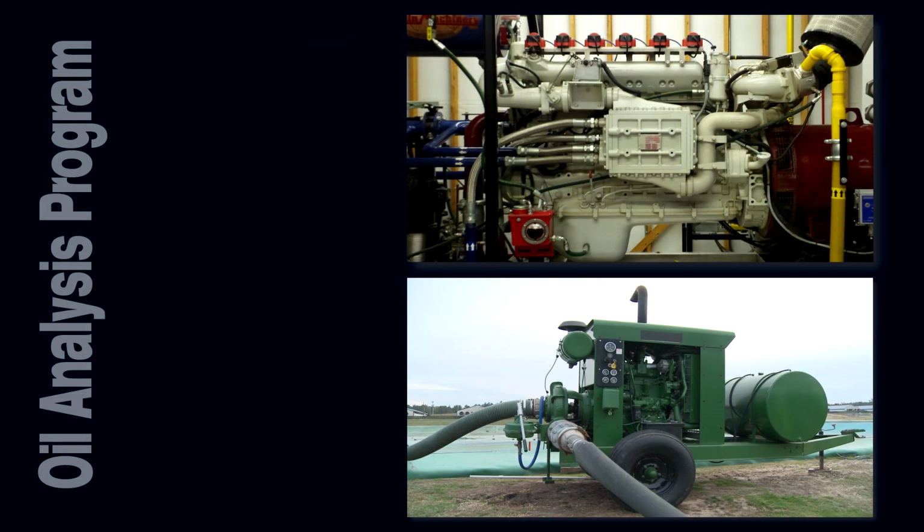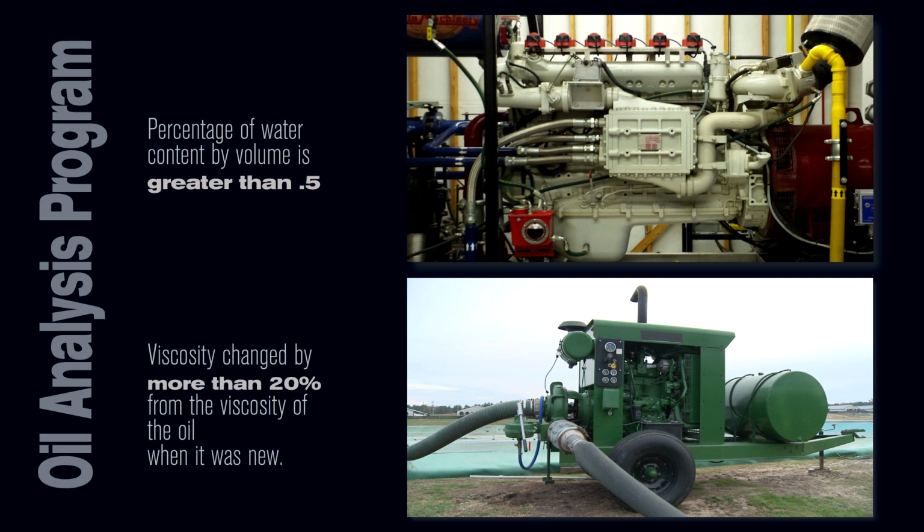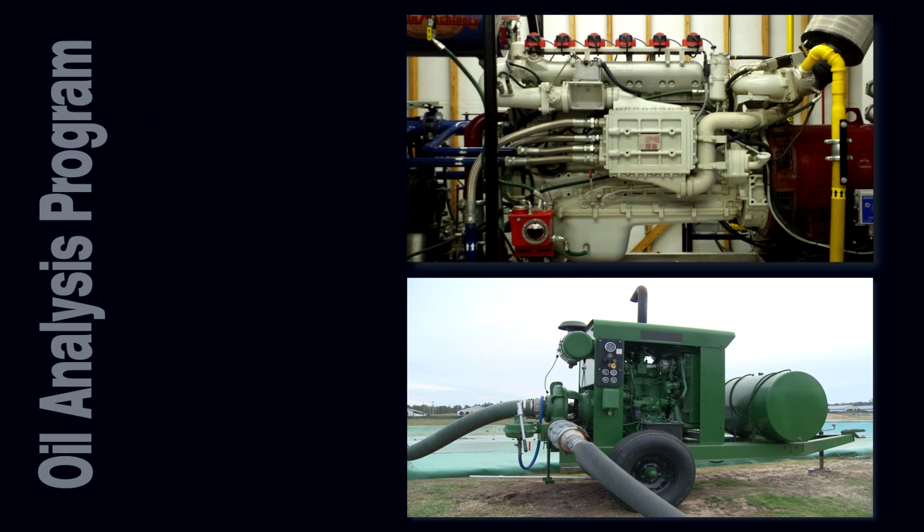Must the oil analysis be performed at the same frequency as specified for the oil changes? Yes, it does. And if the analysis fails to meet certain limits, then the oil needs to be changed within 2 business days. And what are those limits? Well, the limits are the percentage of water content by volume is greater than 0.5. The viscosity of the oil changed by more than 20% from the viscosity when it was new.